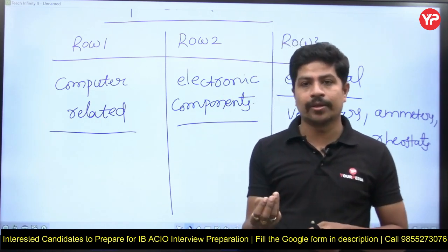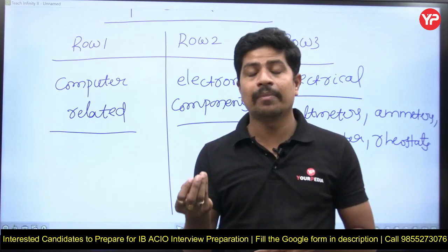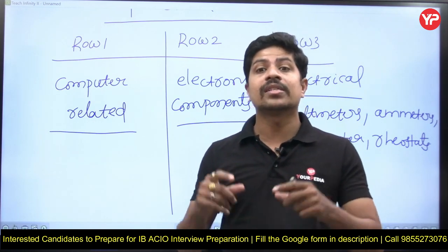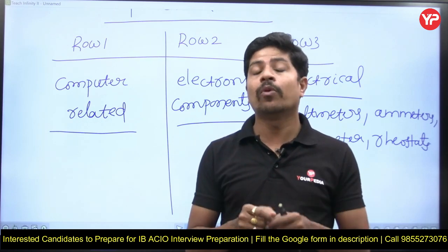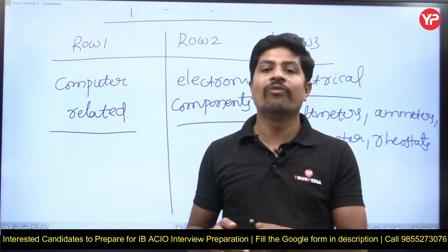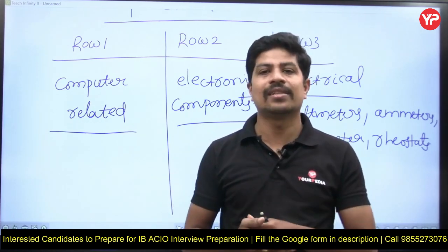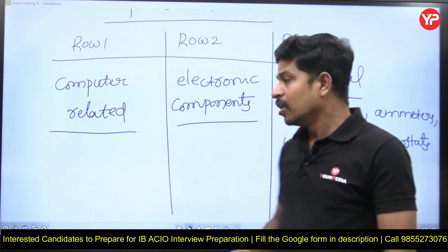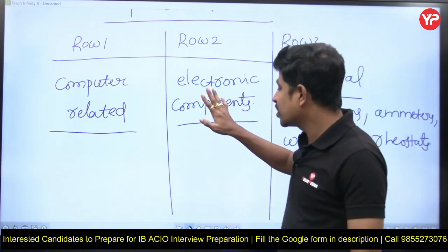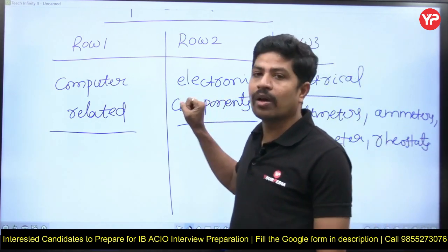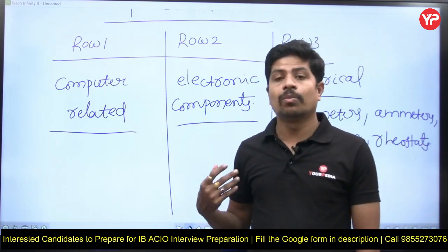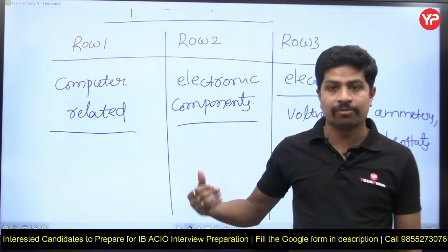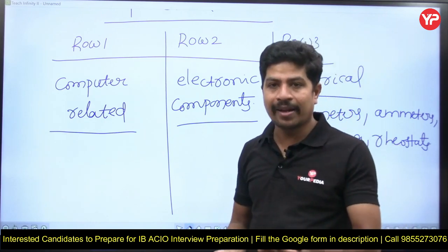Suppose there is a capacitor, a resistance and a BJT, configure all these on a breadboard, how to create a common ground on the breadboard, how to connect the breadboard equipments to the oscilloscope where you are going to see the results, and how to connect the DC supply. More or less it is your EDC and analog electronics laboratory, which you studied in your bachelor's. So you must be thorough with all the experiments of your EDC subject and analog subject.